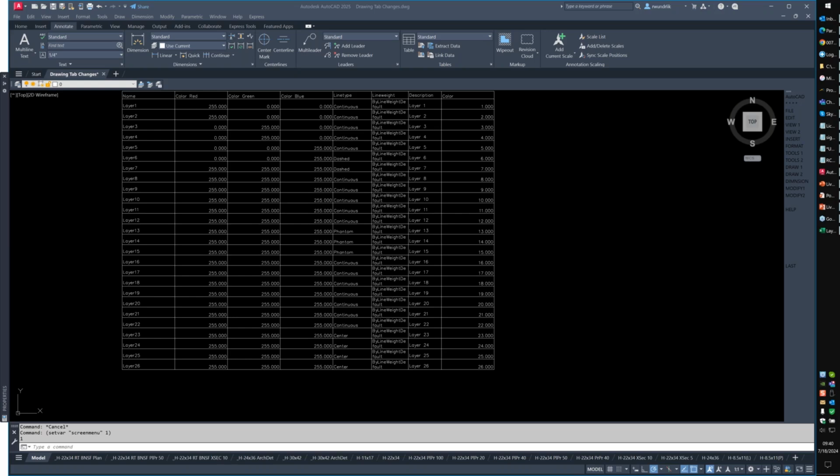I prefer to keep my AutoCAD stuff in AutoCAD as AutoCAD entities. I prefer to use AutoCAD tables because I have all of the table controls, where if I'm just bringing in Excel, I'm relying on Excel to handle the formatting.